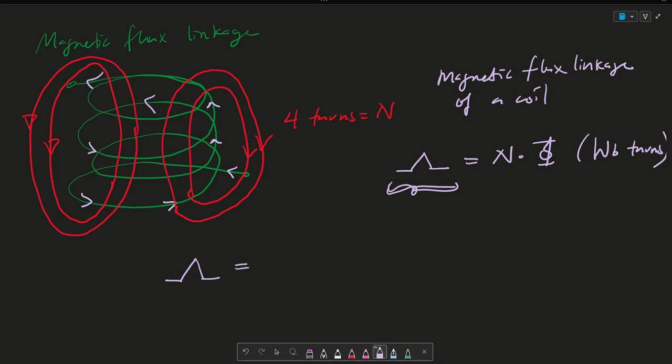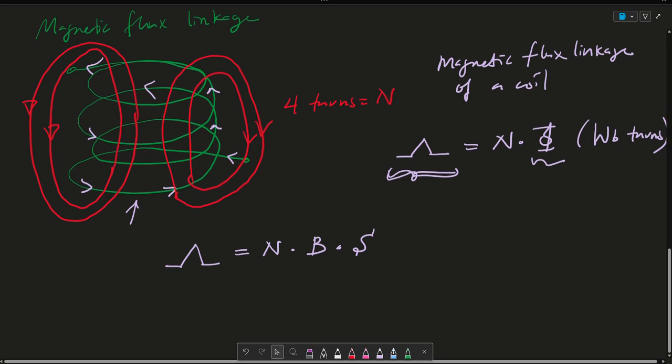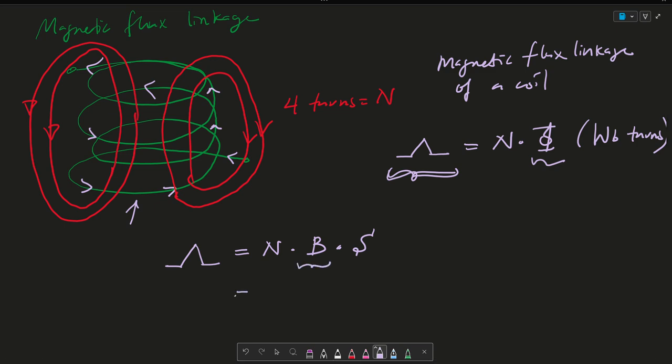So then this equates to the number of turns times, I'm going to replace the magnetic flux with the magnetic flux density B times the cross-sectional area of my core, in this case, it's just air, times S. So then let's go ahead and define the magnetic flux density. And this can be defined as N times mu H, all right, times, again, cross-sectional area.